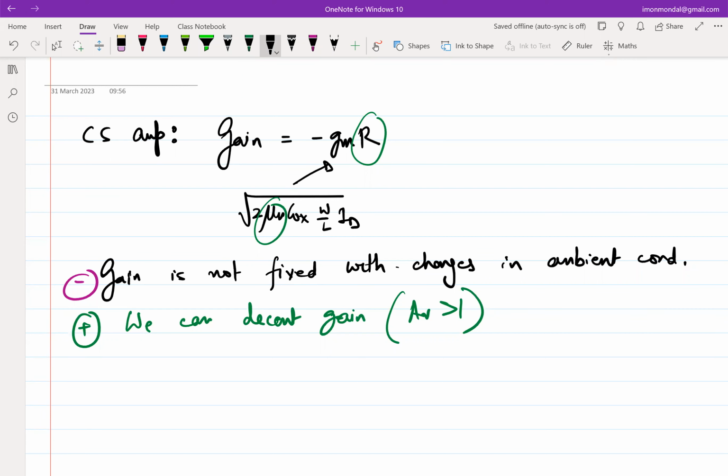However, forget about this amplifier business. Given that you know the components that we use in circuits, resistances, capacitances, MOSFETs, and you know the MOSFETs also have certain characteristics, you should be aware that none of these characteristics, neither GM nor R, not even capacitance or inductance, are stable with temperature. All of them vary with temperature, right? So the question that naturally arises is, if everything varies with temperature, how can we even think of making an amplifier whose gain is stable?